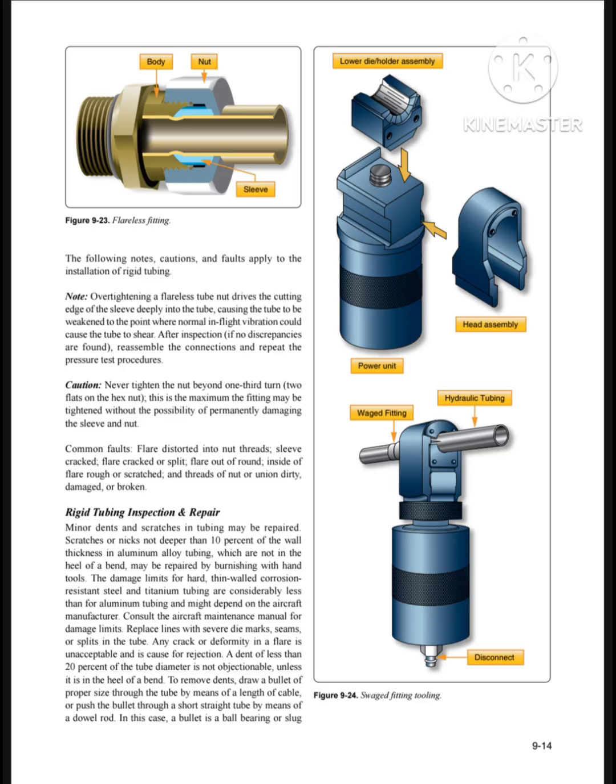And for 2190 for example, it is a design part adapter, flareless tube to AN flared tube. And the prefix MS is also known as military standard specification, which has been shown in this video, and so on. It is just an identification of the parts and a typical MS flareless tube fitting.